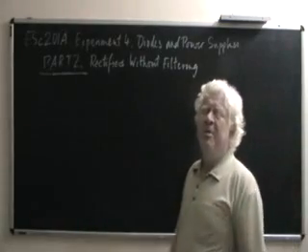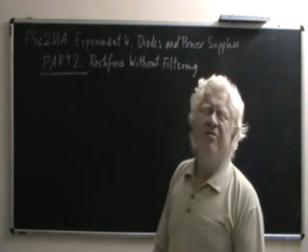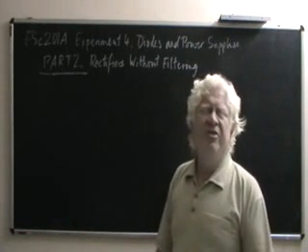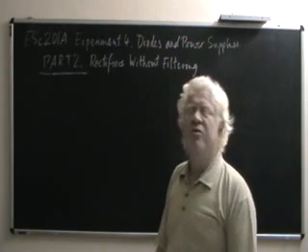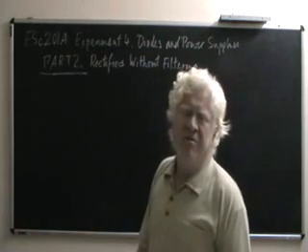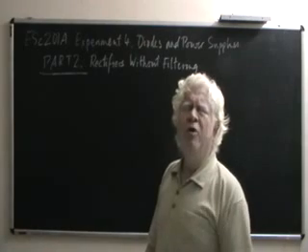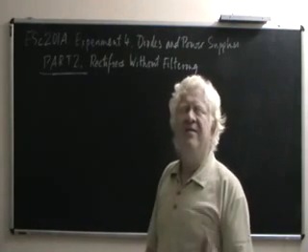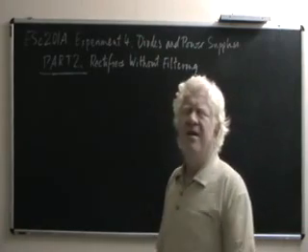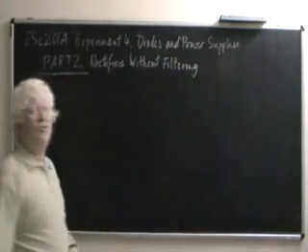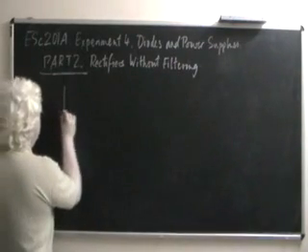The second part of the experiment consists of building a rectifier. What is a rectifier? A rectifier is a circuit that converts alternating voltages, that is voltages which go both positive and negative with respect to the other terminal, into a voltage which always has the same polarity, though not necessarily the same magnitude. Let's take an example. If you take a sinusoidal voltage, then its waveform would be like this.